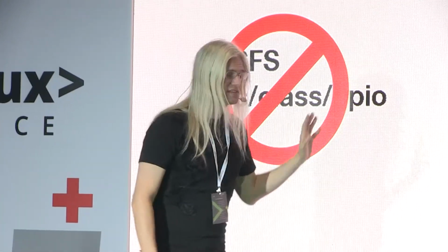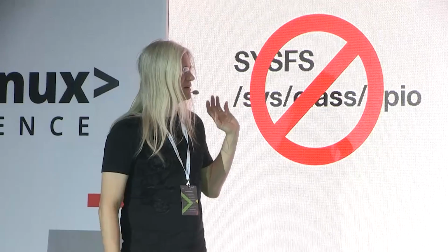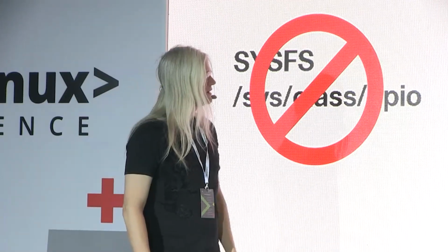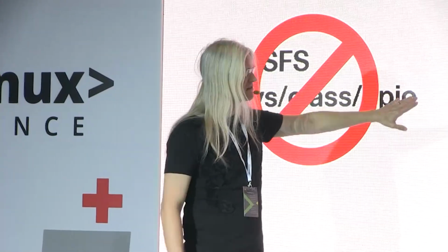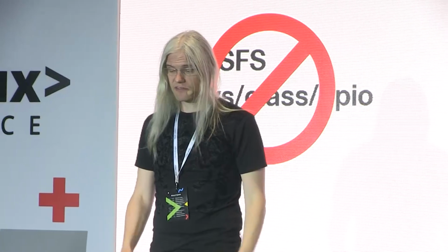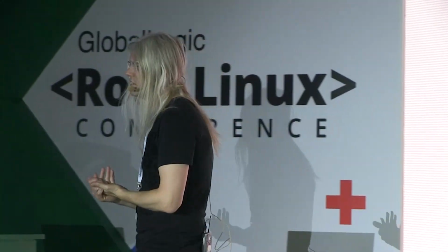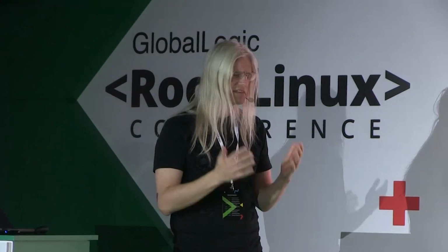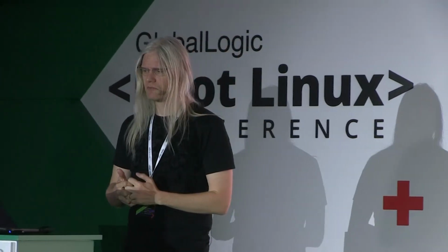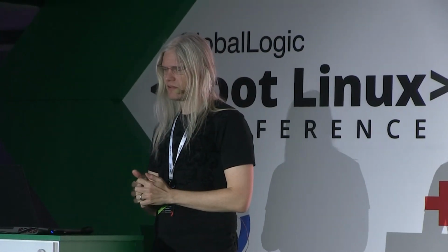And I got this problem, and this is the biggest problem that I'm now working to resolve. Instead of using that, we have a character device, which we use ioctls to control the GPIOs with. And this went into kernel 4.8, I think. And since then we have been trying to promote it. It's getting there. We have some ways to deal with it.